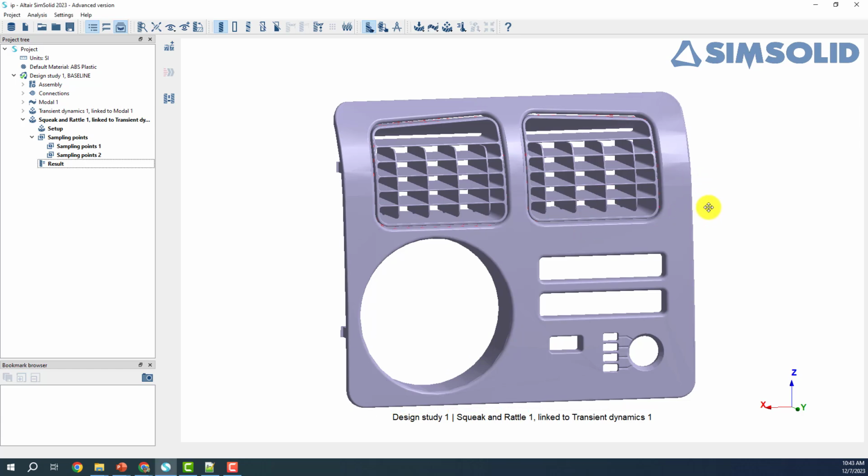And of course, these results can be used as a reference for the FE validation in the future. As a screening, when we reach this level, we can reduce the areas and the points that we want to evaluate. I can do this screening here in the CAD, and then when I jump into the FE validation, I will create fewer sampling points and fewer areas that I need to evaluate, because I know that certain areas are already safe. I am only worried about certain critical points.